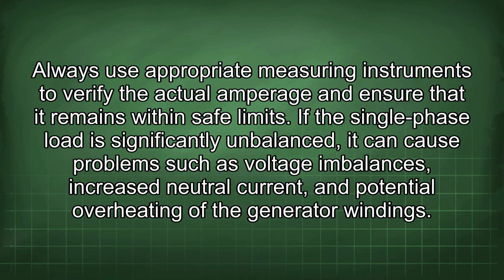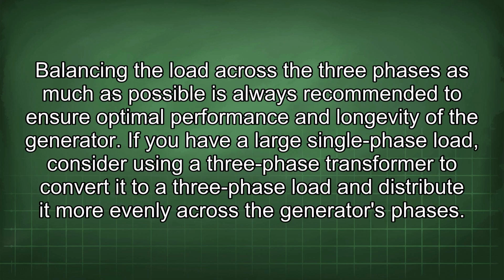If the single-phase load is significantly unbalanced, it can cause problems such as voltage imbalances, increased neutral current, and potential overheating of the generator windings. Balancing the load across the three phases as much as possible is always recommended to ensure optimal performance and longevity of the generator. If you have a large single-phase load, consider using a three-phase transformer to convert it to a three-phase load and distribute it more evenly across the generator's phases.